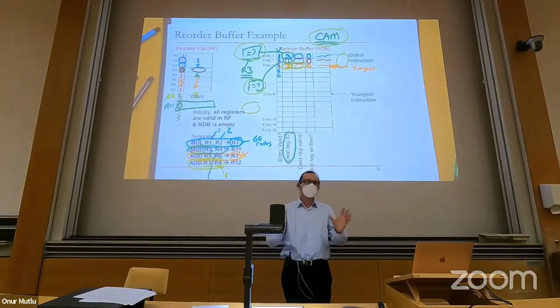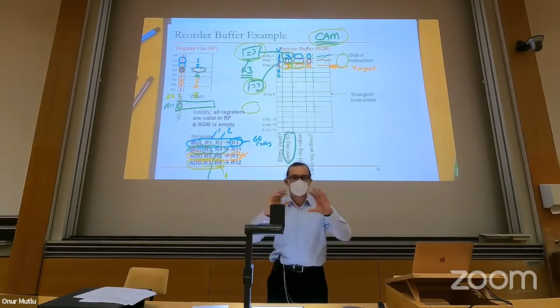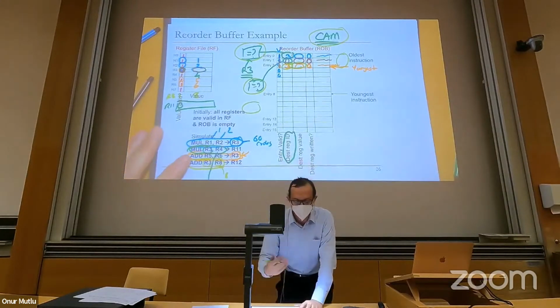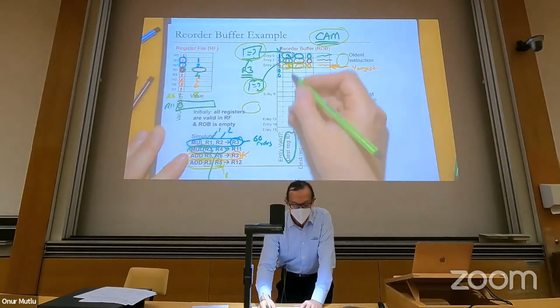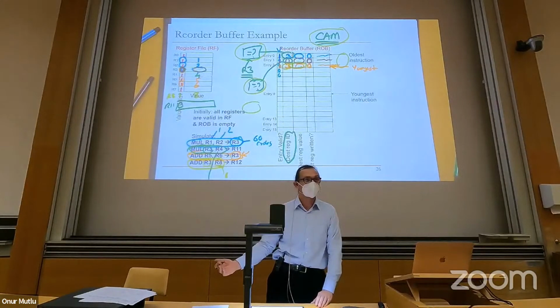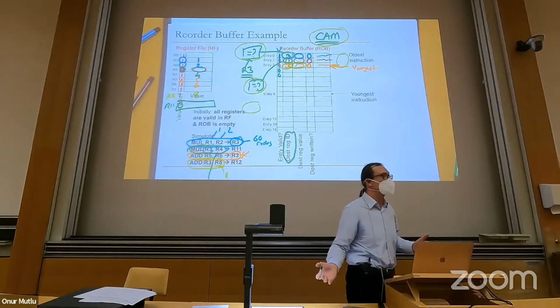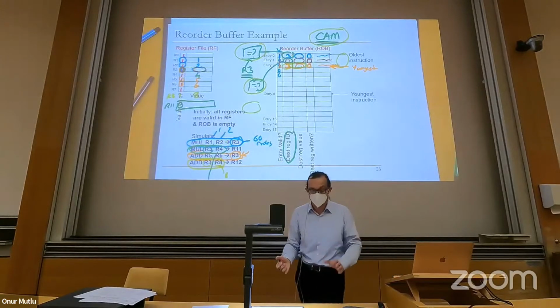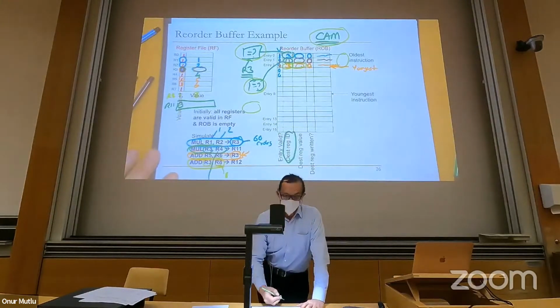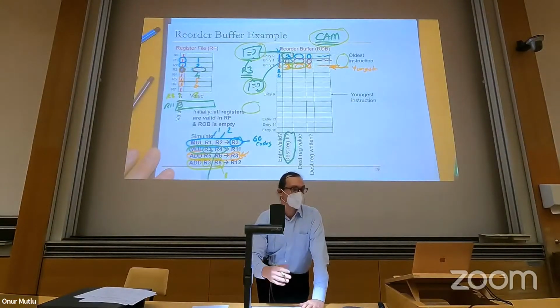So in hardware, you can think about how to do this. It's actually a priority-based, let's say, muxing. You can actually implement it in multiple ways. But this search is not just a content addressable search, but it's also a prioritized content addressable search. Does that make sense? That's what makes this complicated, actually. It's not easy to implement this. 16 entries, 16 comparators. 500 entries, 500 comparators.